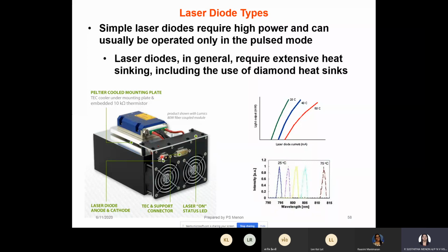The laser chip is very small, but the cooling system is so huge because they want to reduce the amount of temperature. Why? You can see here, this is the lasing wavelength. But when the temperature increases, the wavelength changes. So what happens when the wavelength changes? If you're transmitting data and the data is transmitted at this particular wavelength, when the wavelength changes, the data does not get transmitted. So that's why it's very important to cool the lasers down so that the emission happens at the same wavelength at the correct intensity.